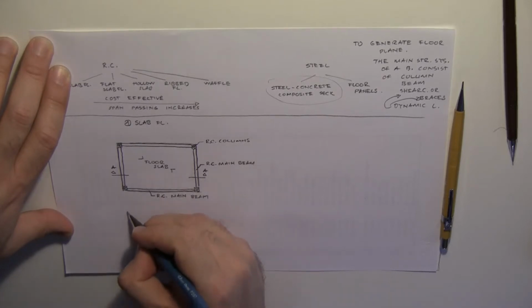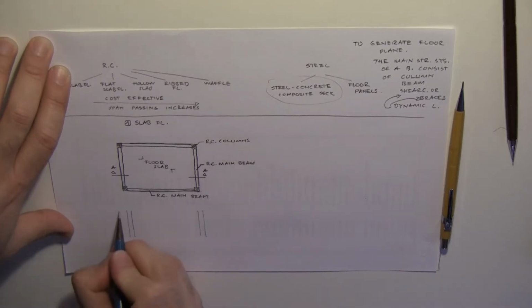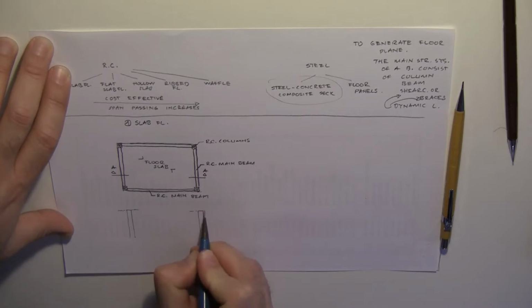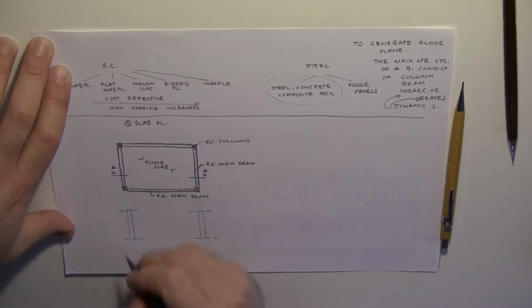In architecture, we firstly draw the elevation lines. These are the elevation lines representing the columns. They continue up and down. This is an intermediate floor, let's assume. I put here dashed and dotted lines to represent that the columns continue upwards and downwards.